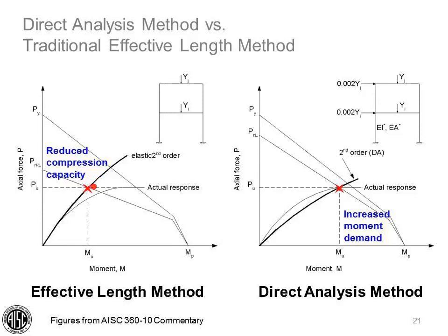The lower sloping line is the strength check. The lower sloping line for the strength check represents the member strength interaction curve using P nominal based on an effective column length of K times L.